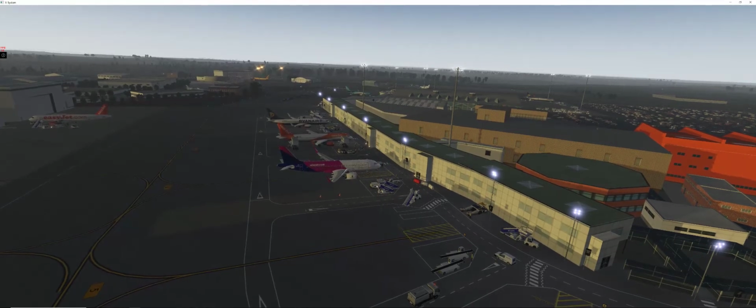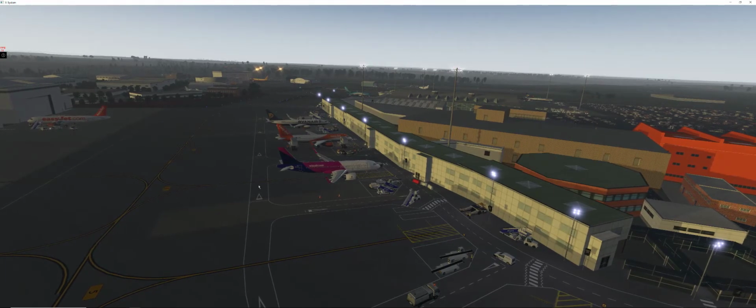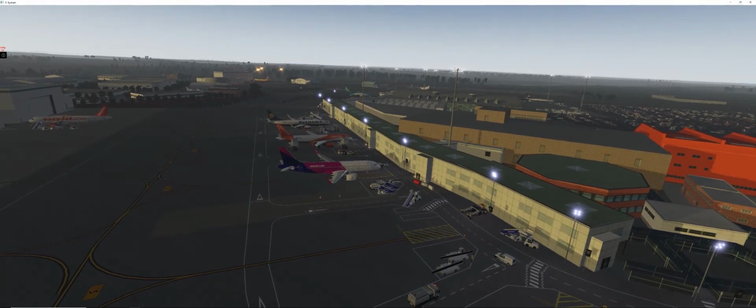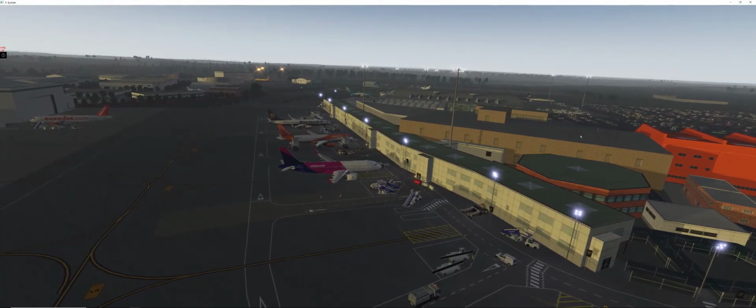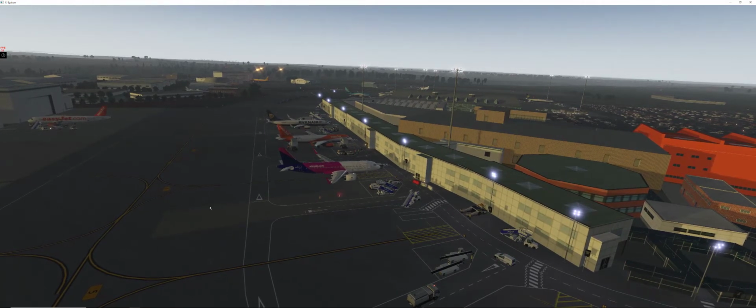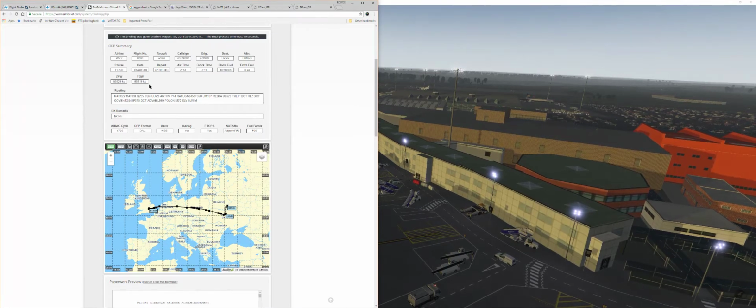So basically when you taxi from here to the runway, if you use 10 kilograms of fuel, then just minus 10 kilograms. And then, of course, when you're taxiing back, once you arrive, then you will have another leg of taxi fuel, but you don't calculate that.